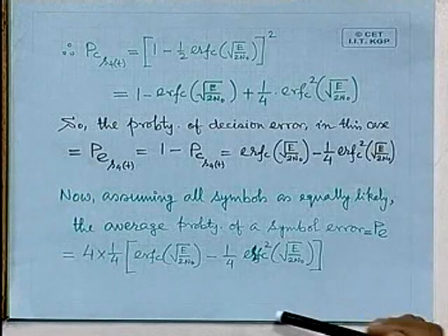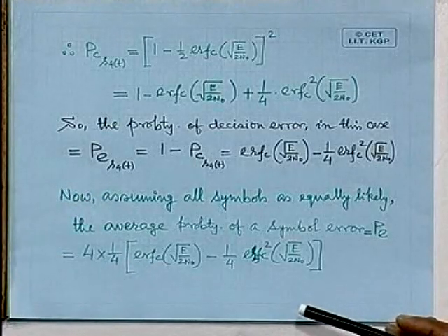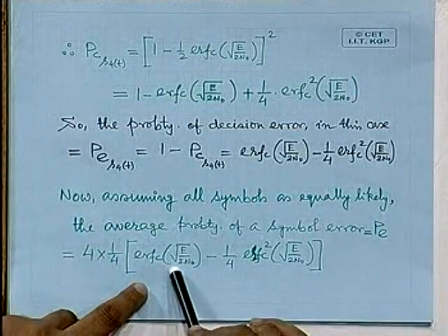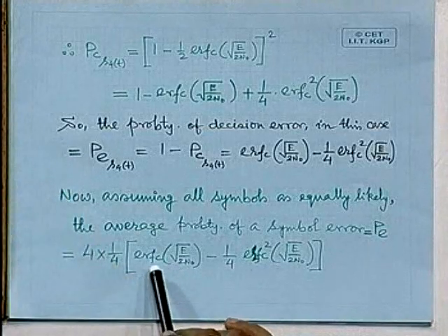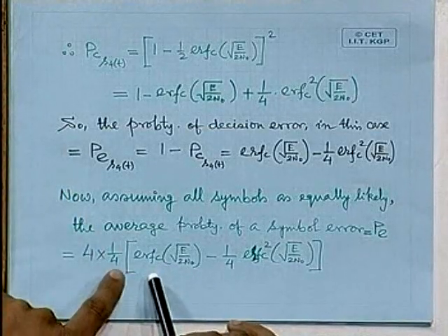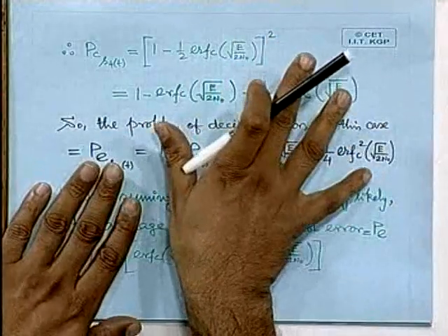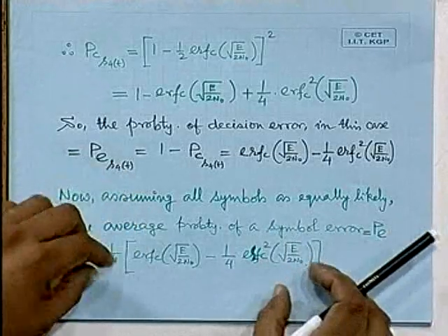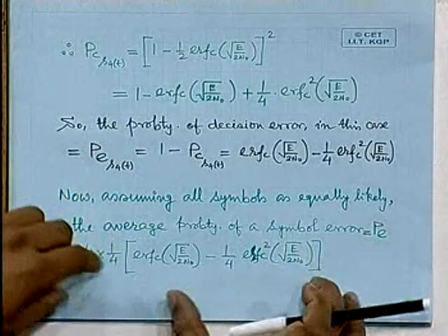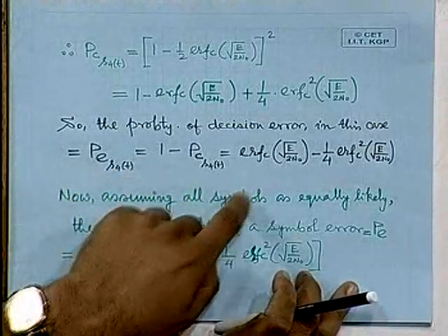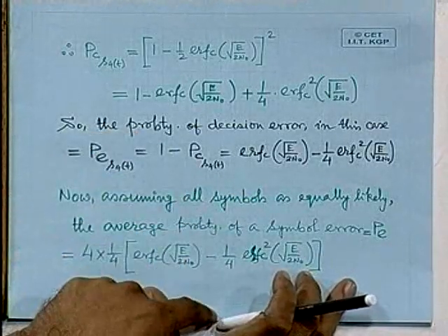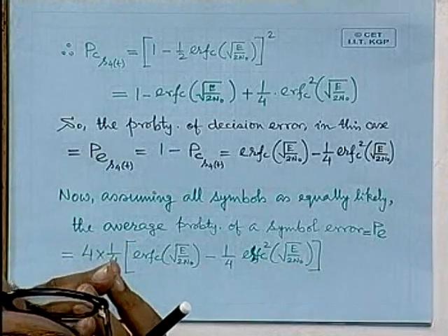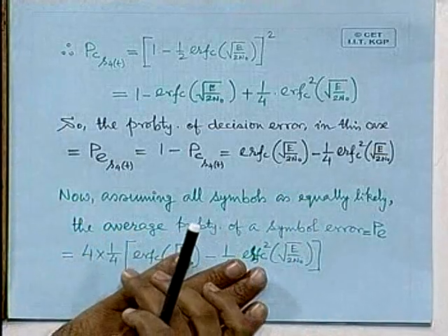What you mean to say is that the sum of the probabilities of the symbols at the input to the modulator is always 1. That's well taken. But what if they are different? You would have to put in the different values, and in general, if the constellation is not so uniform, you would have to consider the input probability distribution, if this expression was not the same for all symbols. So you have to consider the respective symbols with their respective probabilities. All the symbols are not equally likely. So this will only change by a constant. In this case, it would not change.